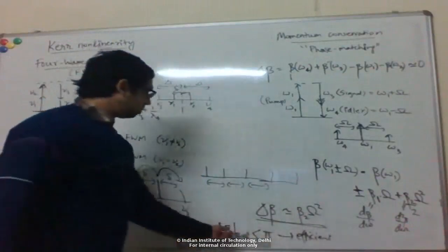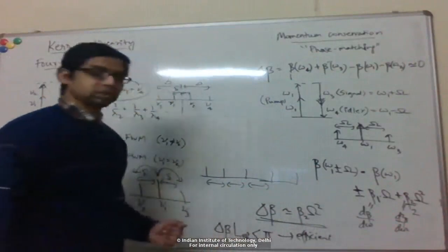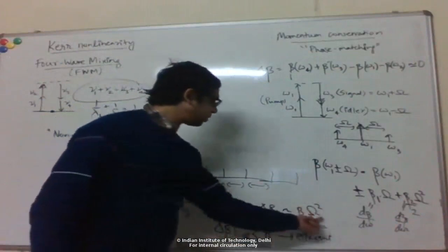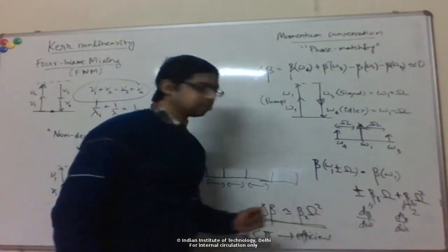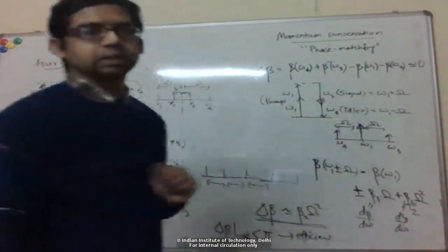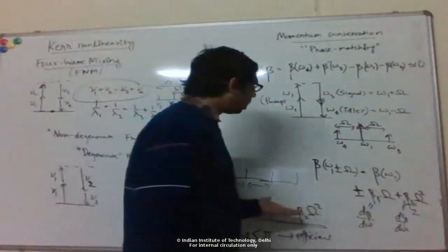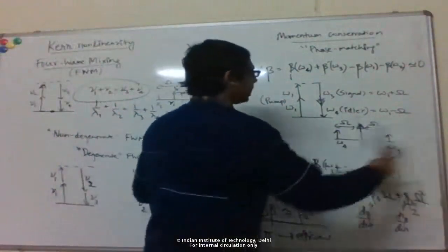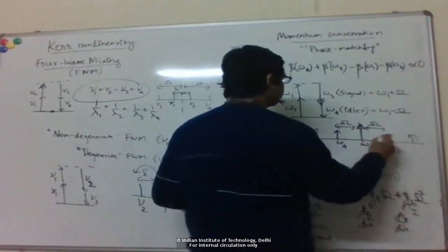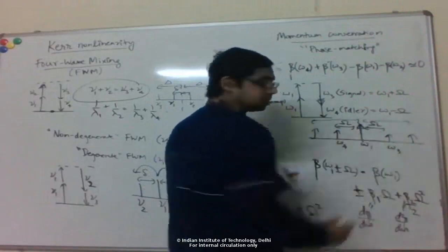So you can see that I want my delta beta smaller than a particular number. If it's smaller than that number, which gives me a frequency range given my beta 2 value, then for that frequency range this four-way mixing can happen. And if the dispersion is smaller, then this can happen for a wider frequency range. Okay, so if you have additional channels here, it could also happen for those. These could also mix.